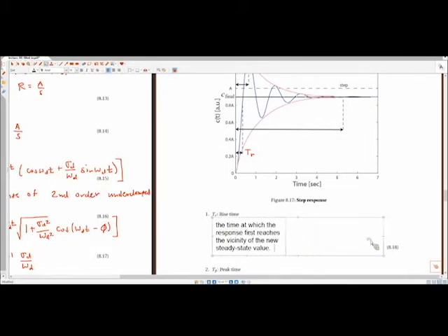Okay, so that means if we make our controller more aggressive, and I think this makes sense, it'll take less time for the response to shoot up, right? Because we've said before, if we have an error of 1, and our proportional gain is 1, that's 1 times that as the input. And now we're saying if we have an error of 1, let's make our proportional gain 5, that'd be 5 as our input. So we've made the control system more aggressive, right? If we increase our proportional gain. Other metrics is peak time.